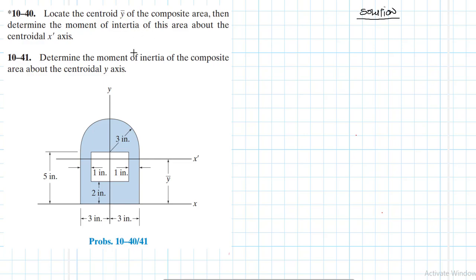And we also have moment of inertia, which we are dealing with, which is moment of inertia of an area, also called area moment of inertia or second moment of area. This is also a geometric property, but a little bit different from centroid. It is a geometric property of a shape or an area, such as the cross-section of a beam, which describes how the area is distributed around an axis, an axis where we want to find the moment of inertia. So we can have moment of inertia about the centroidal axis or any other axis that we choose.